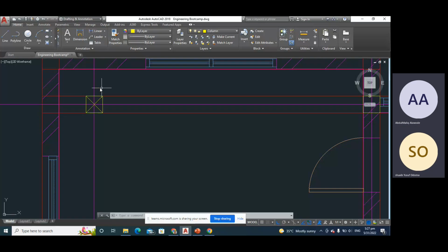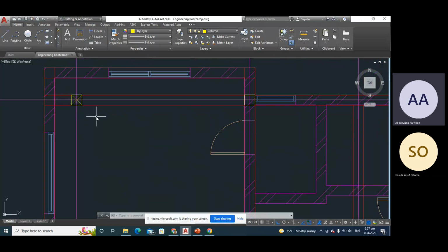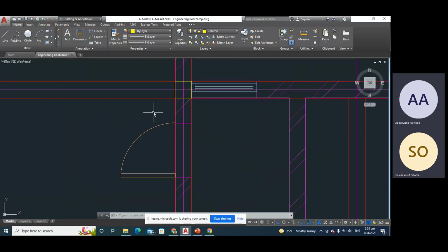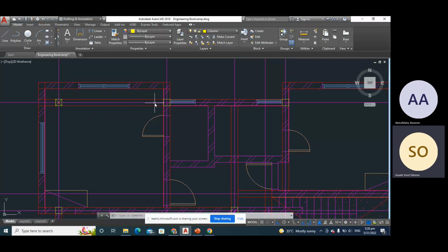Okay, if you see anything like this, what it means is the column terminates on that floor. If you see anything like this, what it means is the column is planted on that floor. So it's starting from that floor. So when they are tying their beam, they should put starter bars inside that beam. That is what is meant by a column planted on beam on site.